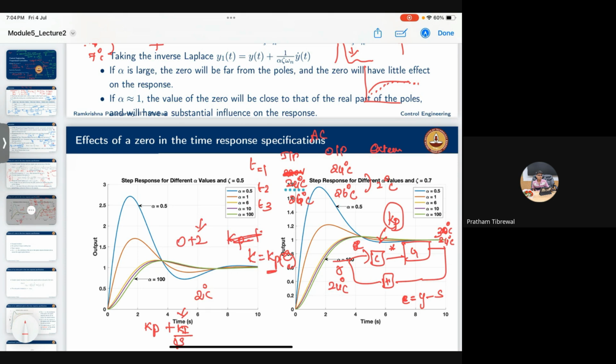After a period of time, I'm speaking about over a looping of time, T4, T5, T6. This will keep track of all the degrees that is being differentiated from the output. For example, after some time it might go to a 10-degree difference, this might go to 35, so this will become 10 or 11. Based on all these things, this will generate a control action based on the error, integrated over the period of time, not like a proportional controller.